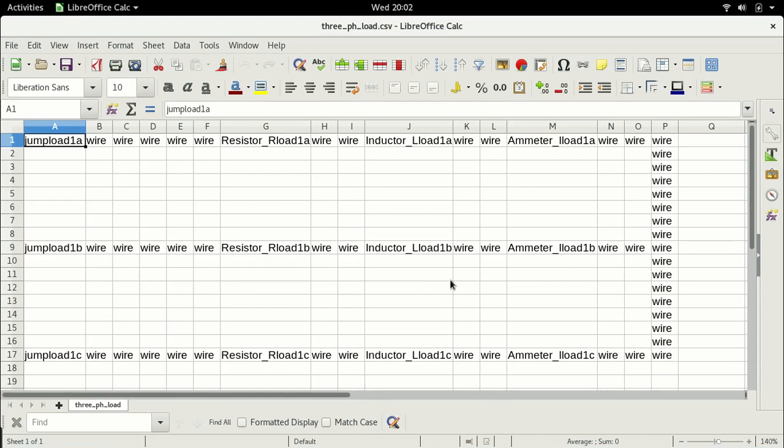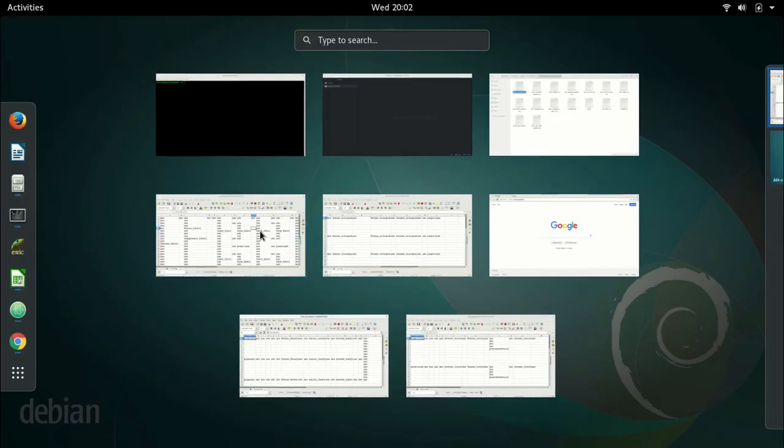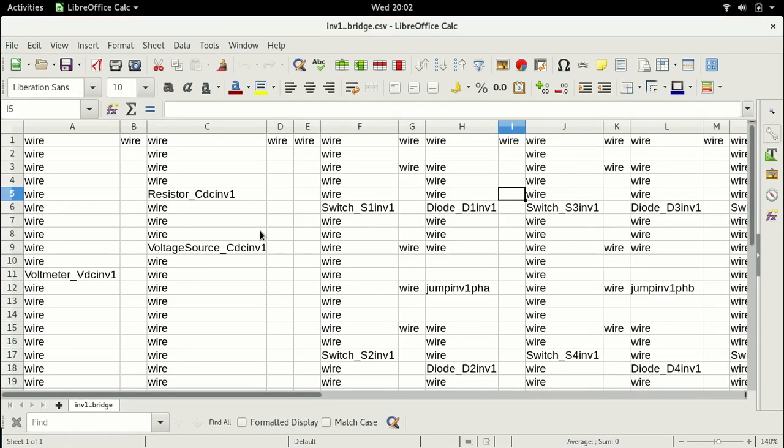Now this is called open loop. Why? Because you are setting an arbitrary input and you are not measuring the output voltage and trying to regulate it. You're just giving some input and seeing the output. This is called open loop. But what we are going to do now is start closing the loop. So in a UPS, the ultimate objective is to regulate the output voltages.